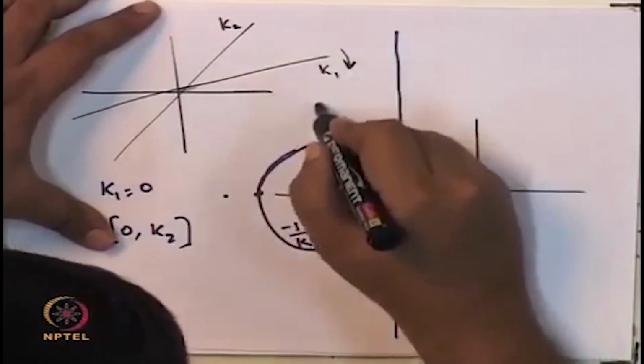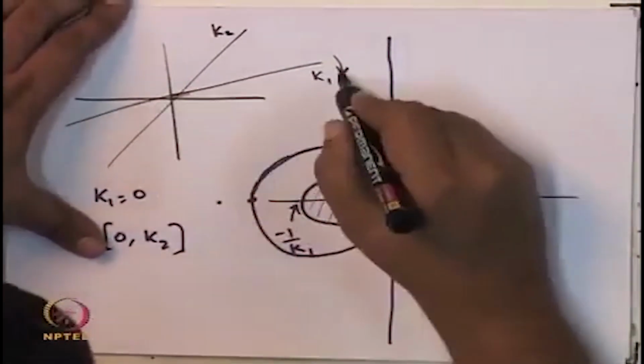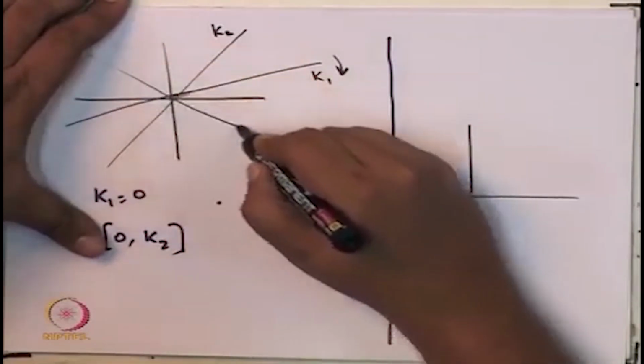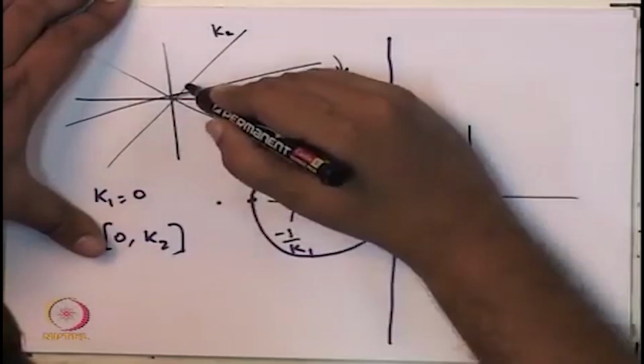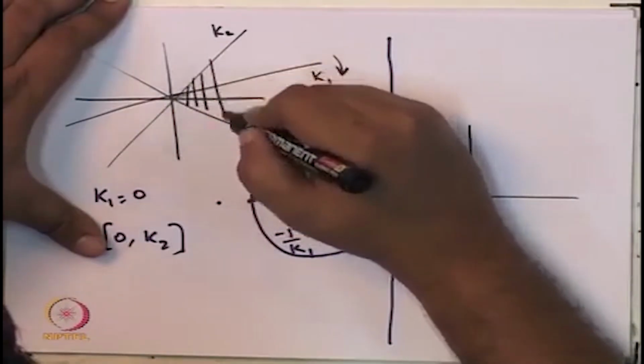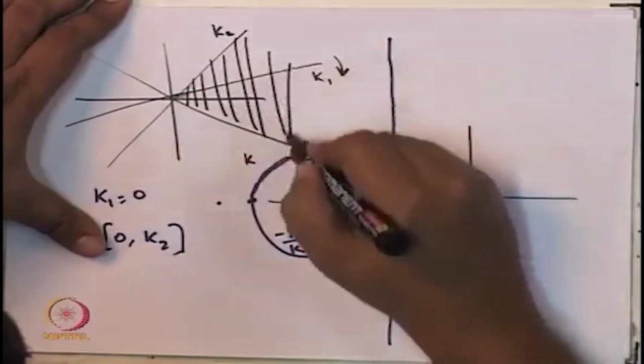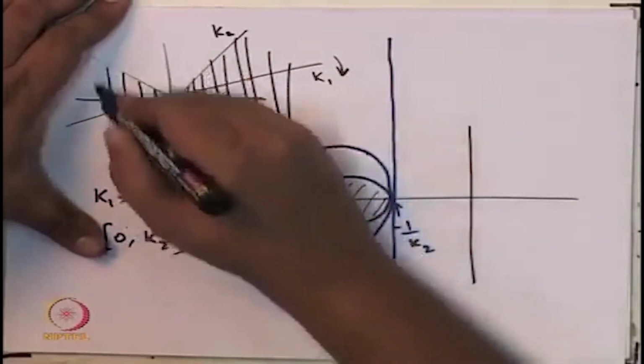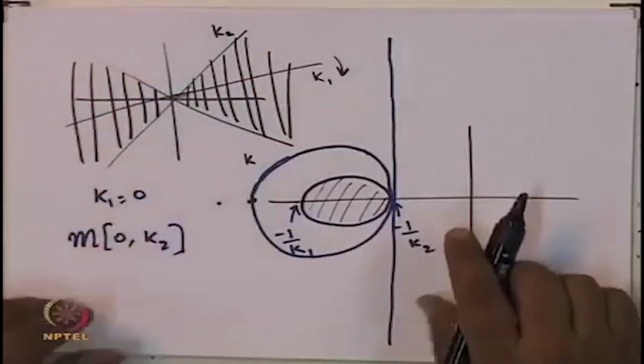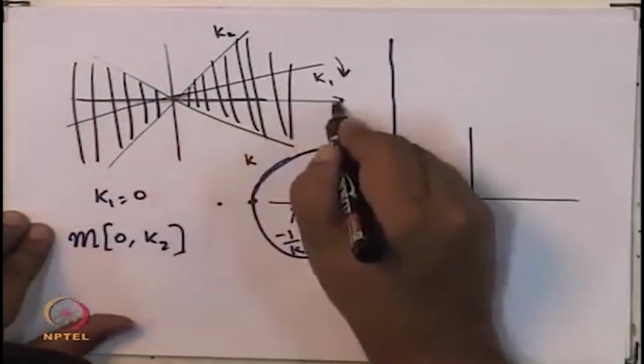So, this result is in fact a more general kind of a result, of which the positive real condition is a special case. But now, interestingly, we can do more things. For example, keep k2 like this, and k1 could be extended to such an extent that k1 in fact becomes negative. So, this is k1. So, one is looking at a nonlinearity which can lie in this whole sector, where this is the 0 slope.